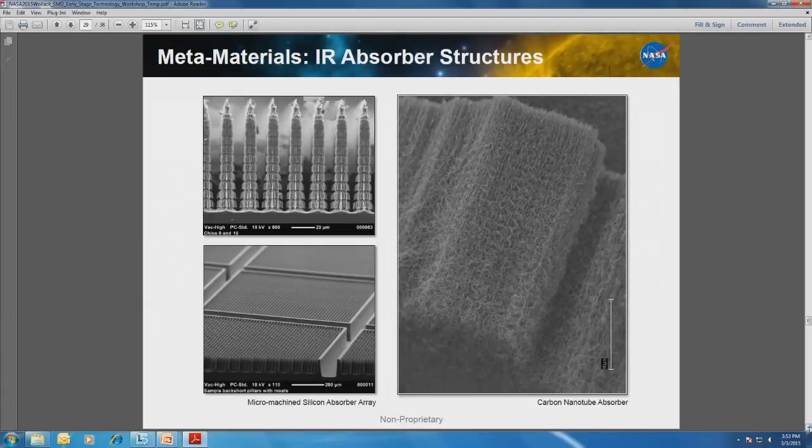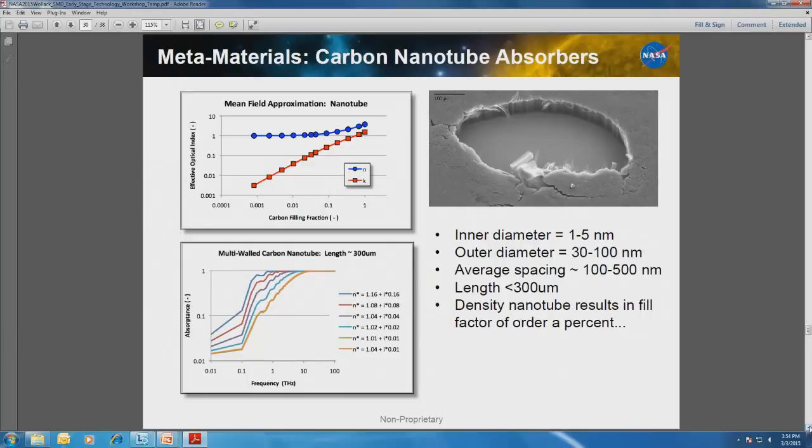And there, in this case, given the bandwidth that was required, a traditional design would have required multiple layers to do this. And it's easier to make this than the other structure. This is a piece of carbon nanotube that has been pulled out and photographed. But if you think about it, it's kind of the inspiration for this part. They're essentially these long needles, the photons come in and they're slowly being absorbed as they go down along the length. Next slide, please. And so for carbon nanotubes, which are mostly used in my lab more in the infrared,